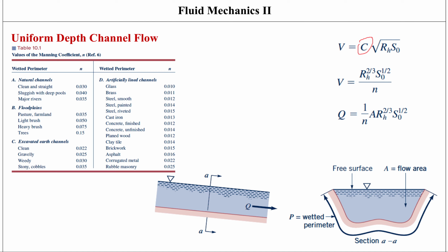Another important thing is that, for example, when we look at the value of n or the value of c, these are not dimensionless numbers. They have dimensions. Usually what we've seen is, especially for pipe flow, we move towards the dimensionless form of the equation. So the coefficients that appear in those are also dimensionless coefficients, like friction factor in pipe flow, or like drag coefficient that we saw for flow over immersed bodies.